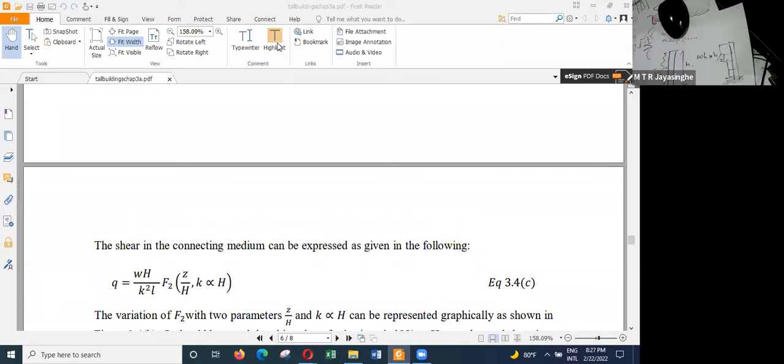So we run the system, and by evening all the batteries are fully charged. So we run the evening peak on batteries, and we find that the batteries become weak around 8:30, depending on the usage. And if the usage is high, we'll add one or two batteries, improve the storage so that we can go until 9 o'clock.